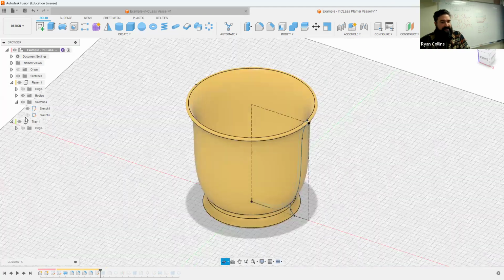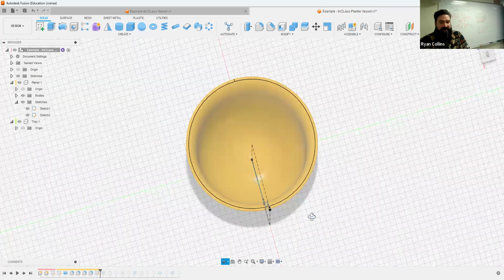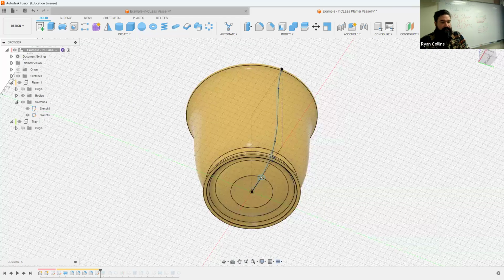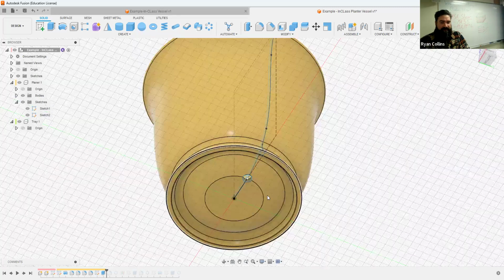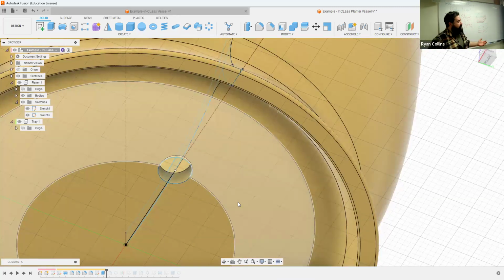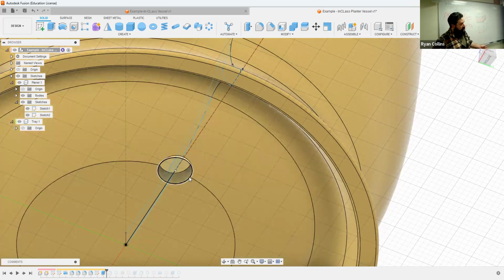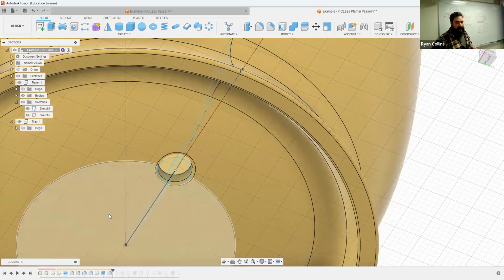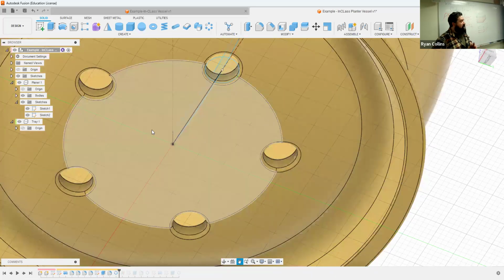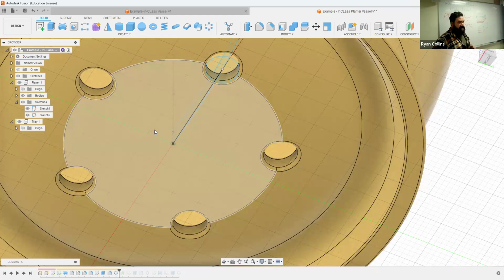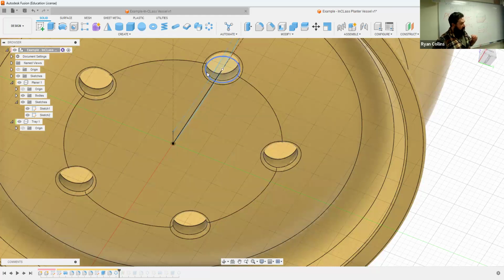Inside, I started creating sketches of where I want to make drainage holes. And what I did is making one extrude through to cut. And instead of making multiple sketches, extruding everything, and just making more work for myself, I make one sketch, one hole through, add anything I want, like the features of a fillet there, and then I repeat that completed thing using the pattern tool and make multiple holes. So I don't have to keep repeating each one all around and all that such. I can complete one whole thing, make it all the features I want, and then just use the pattern tool to repeat all the completed things. Make it easier on yourself.